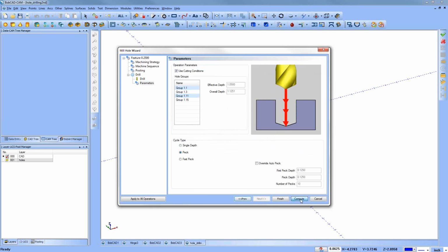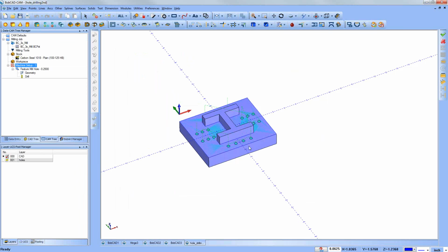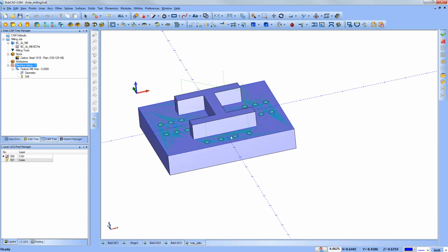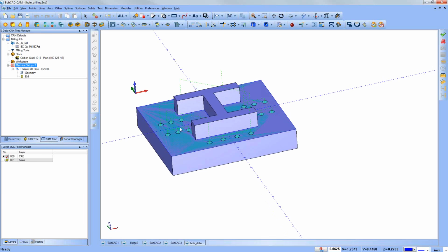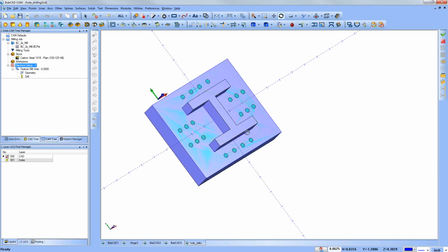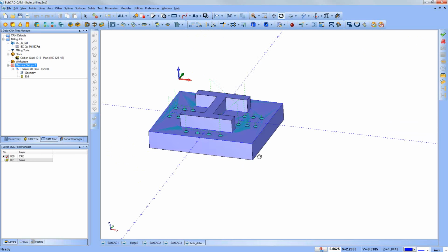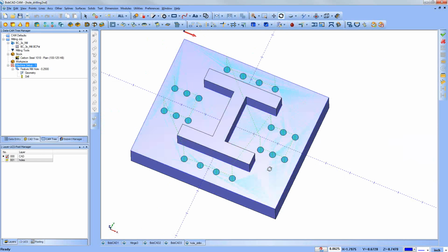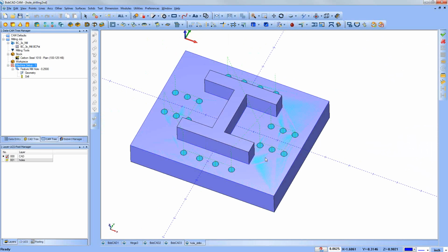I'll do a peck drill and compute that. Okay, so we definitely see a difference of how it's going through and cutting into different groups, right? So it'll cut and start this group, then here, then the third group, then the fourth group. So if everybody can see that, it's avoiding that, yet it's also staying down and efficiently cutting within each group. So that was a question there.